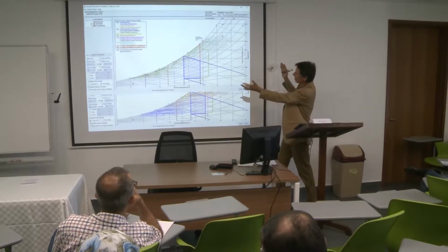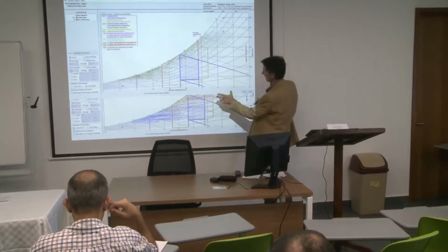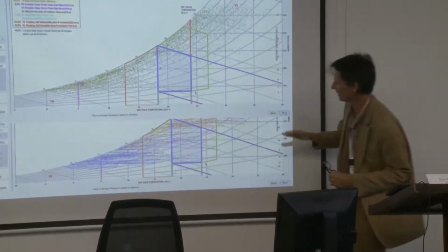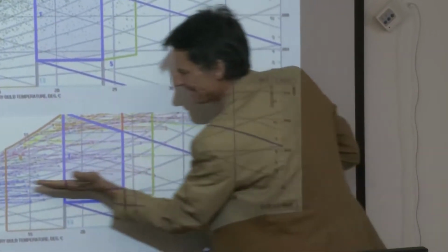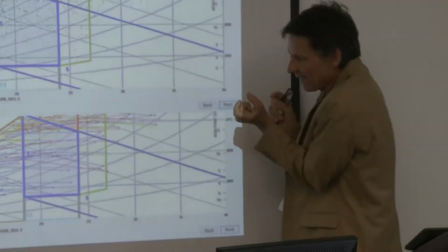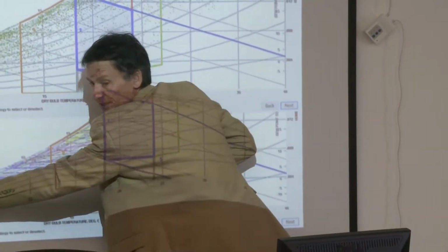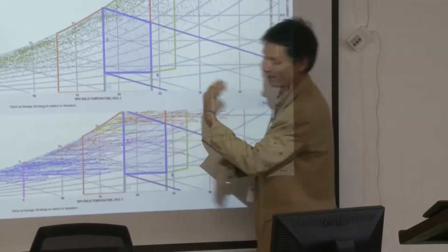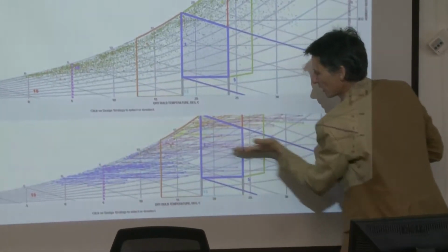Now, looking at the Climate Consultant from UCLA, you get this hourly data, you can just toggle it and switch it so you can show the daily minimum and maxima. And what you find is that in a given day, there's typically a certain amount of water vapor in there. So during that day, it tends to just track along from about sunrise until about 3 o'clock in the afternoon or so. There might be a weather event, and it might reset the moisture to a different point. So it tends to be traveling this way.